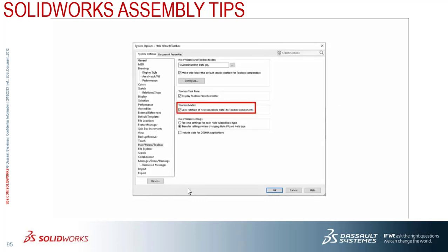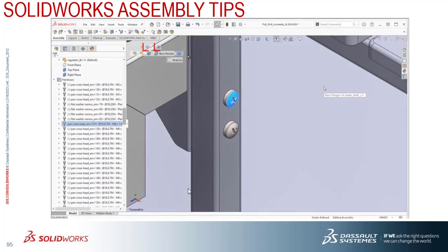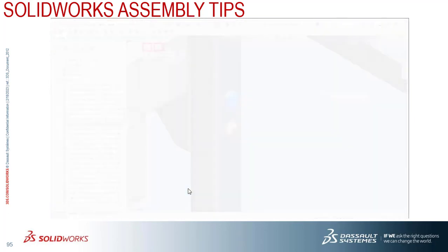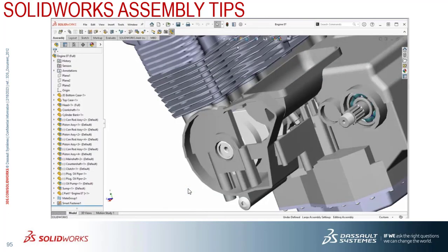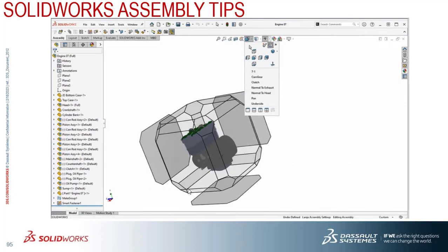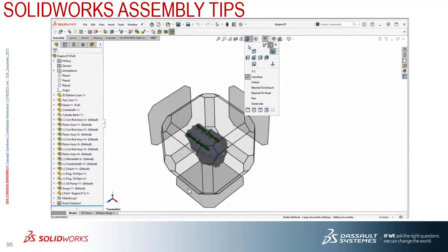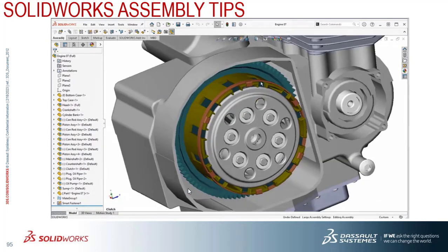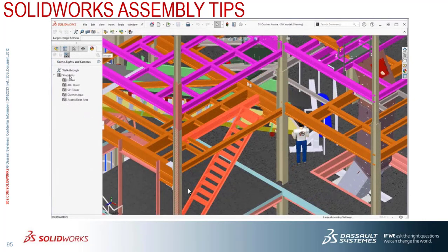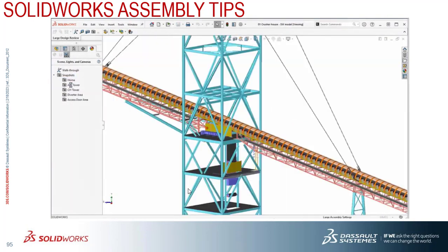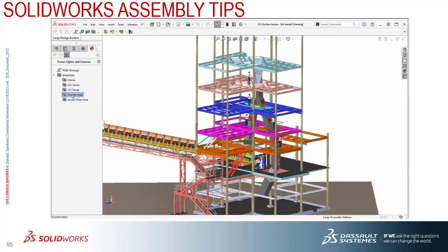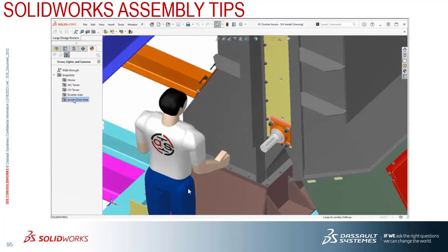I already said that you can lock the rotation for the toolbox component, so it does not necessarily rotate inside the assembly. You can also save some standard views you want to see again and again when you open the file, like customized display views, so you don't need to zoom, rotate and pan. Because you want to see those particular areas, just save them as display views, so you can very easily navigate between those views.